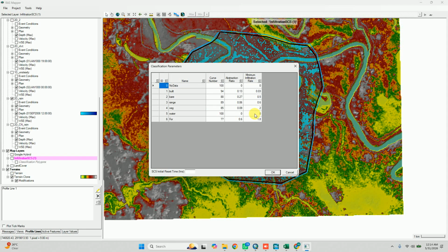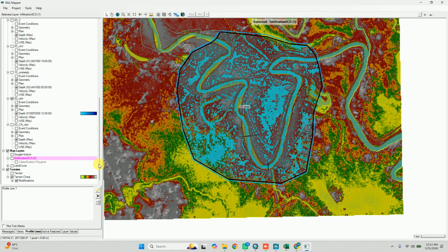Here there is no infiltration, as it explains, there is water, infiltration is choked over there, constant infiltration is taking place over there. And similarly for vegetation, there is an infiltration rate of 2 mm per hour. Where water stops for more time, infiltration will be more. In forest area infiltration will be more, but in built-up area there will be very little infiltration. So less infiltration takes place here. So this is the data you have to provide to the model, and how I have created this data, how you can create all this data.